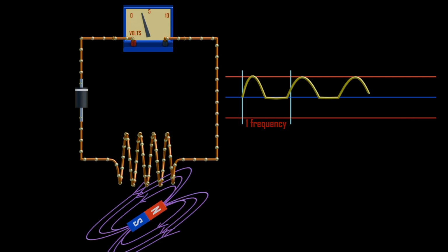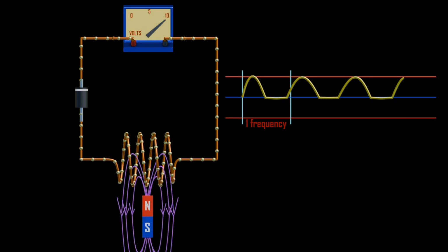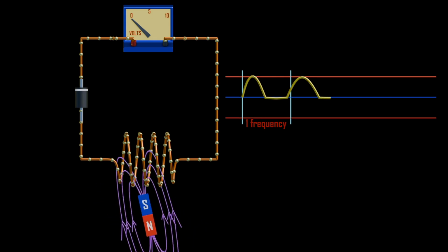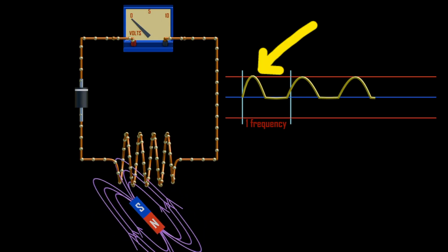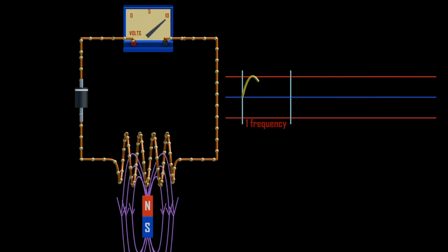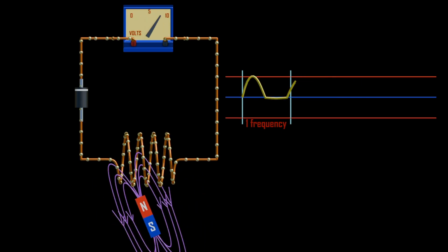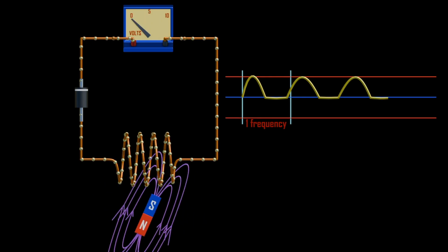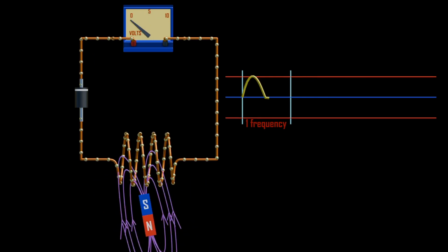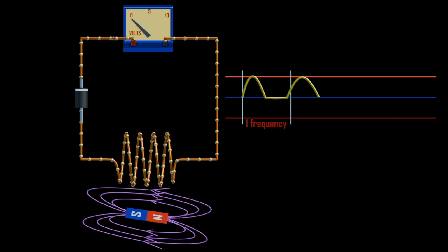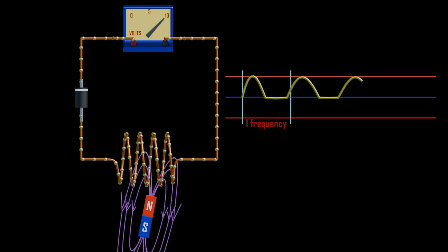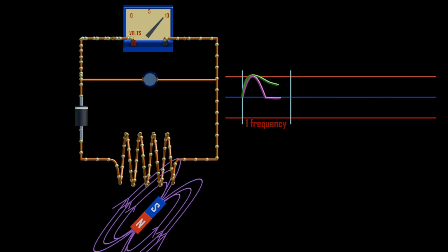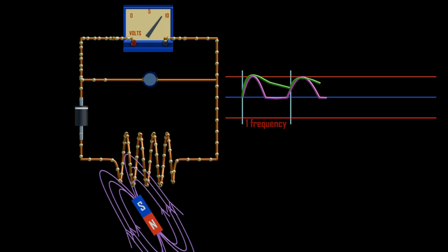If we achieve this DC current with one diode, which is responsible for current blockage, this is what we call half-wave rectification. In half-wave rectification, during the positive half cycle of the AC sine wave, the diode is forward biased, since the anode is positive with respect to the cathode, resulting in current flowing through the diode. While the output of a rectifier is a pulsating DC, most electronic circuits require a substantially pure DC for proper operation. The pure DC output can be provided by a single or multi-section filter circuit placed between the output of the rectifier and the load.